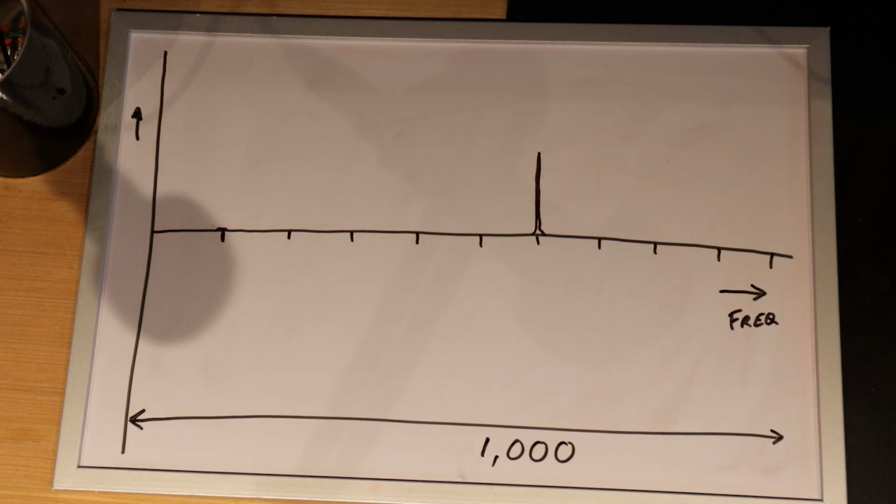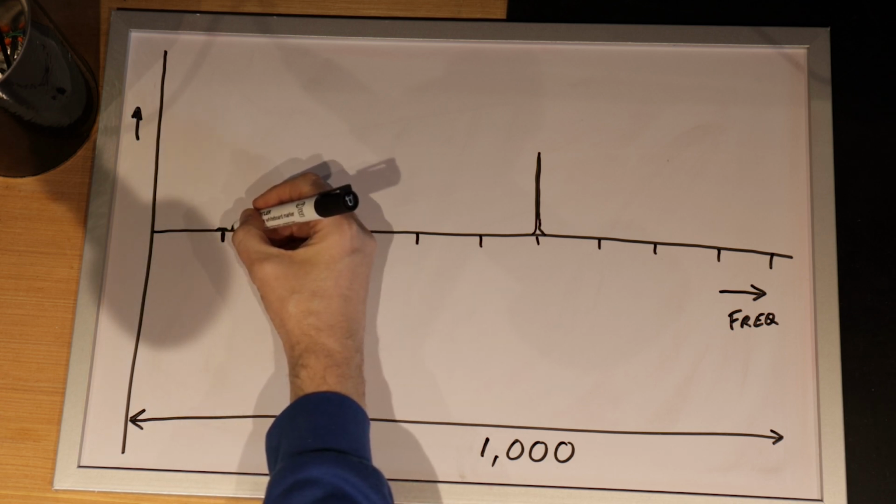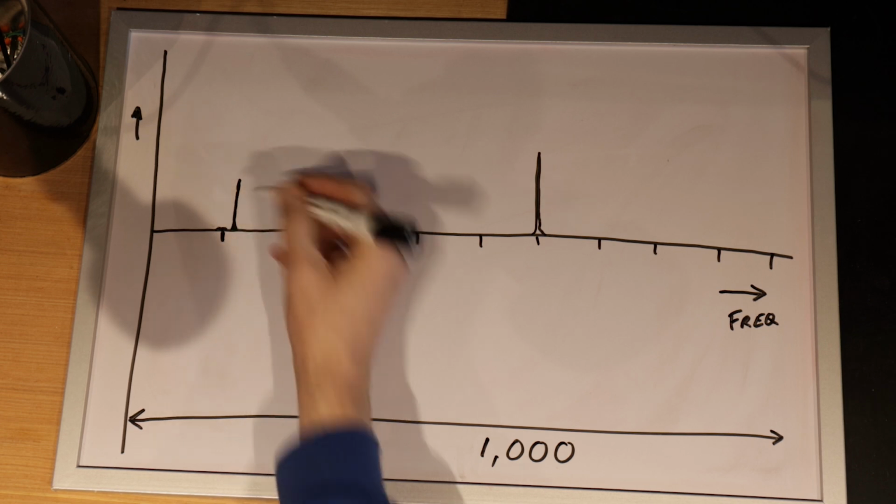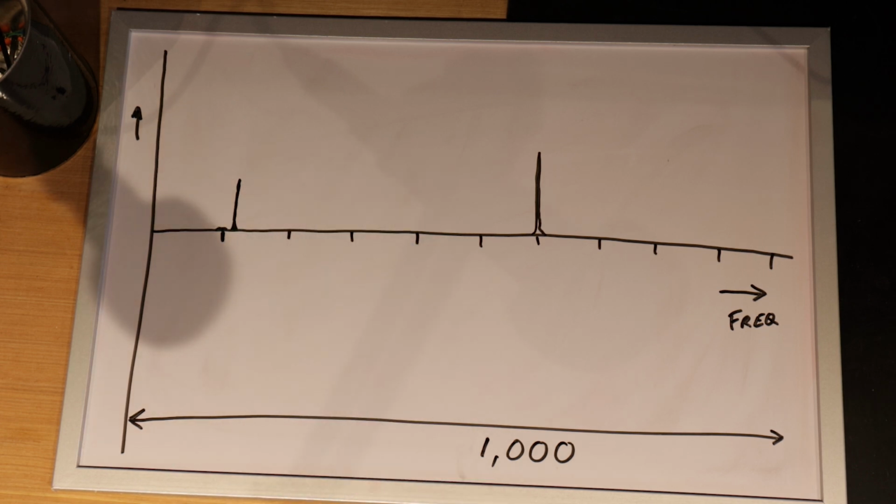but we're getting some hum, and we don't know whether the hum is 150 or 120 or 60, depending on your mains. And that would allow us, by knowing that, to see whereabouts in the circuit that hum is being created. Now, if we can see a spike there at 120, we know that the spike is at 120, and that can basically show us where in the system, in the power supply, the fault occurred.